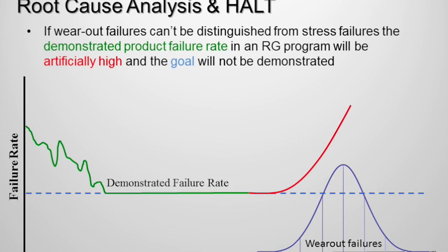Used in conjunction with HALT testing will have given you this great opportunity to observe stress relationships to failure modes. And it will be very helpful in defining your root cause analysis techniques that would allow you to, with confidence in your reliability growth program, distinguish between these two and ensure what's on this graph doesn't happen. And you're only reporting the true failure rate during useful life.